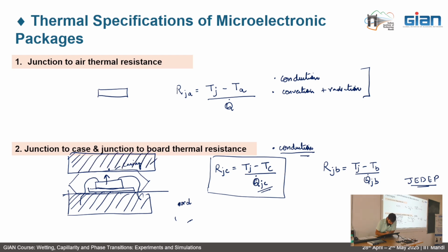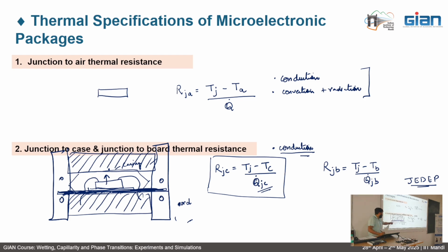Of course, in this case we have a board. And then on this side we have liquid channels, and here we have water channels. And then a specified amount, or flow rate, of liquid is flown from these channels, so that this is a cold plate. This is maintained at a lower temperature. And then the heat transport route would be from the die through this board to this cold plate.